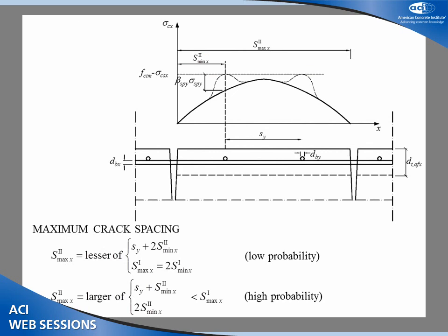For the maximum crack spacing, a new theory is proposed. If we have a setup of the crack arrangement like this picture, then no additional crack can form between these two cracks, because the stress just comes short of the tensile strength of concrete. But we believe that this arrangement has a very low probability, and a higher probability is for at least one of these cracks to happen at the location of transverse reinforcement. So in that case, the equation would be the second one.